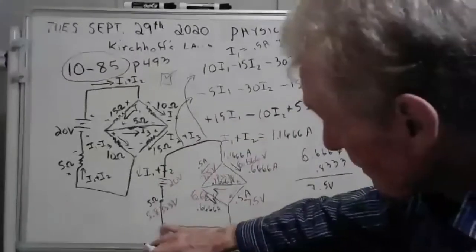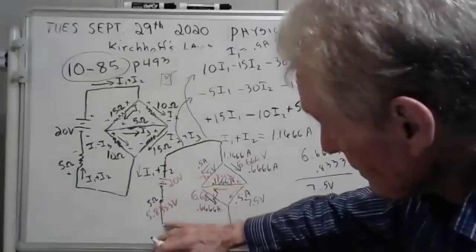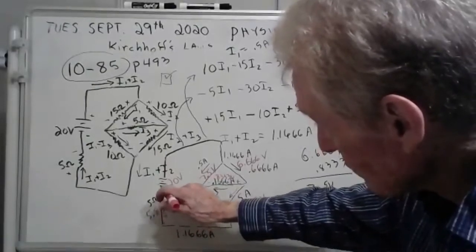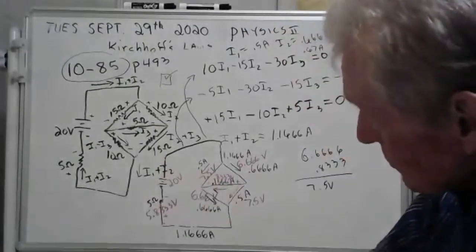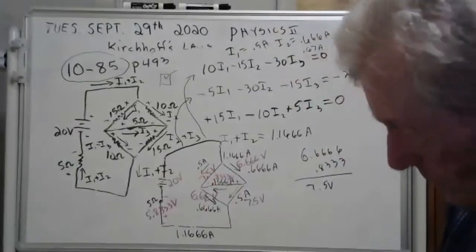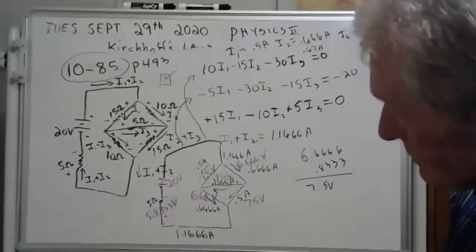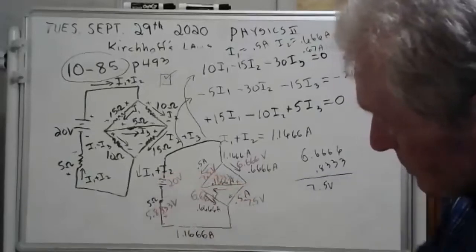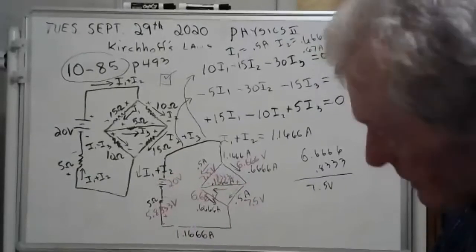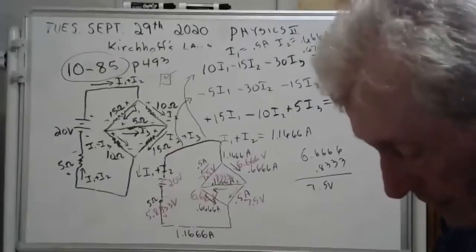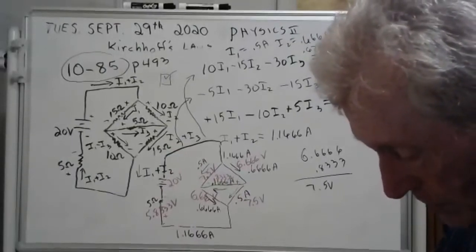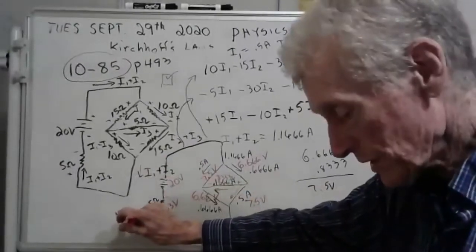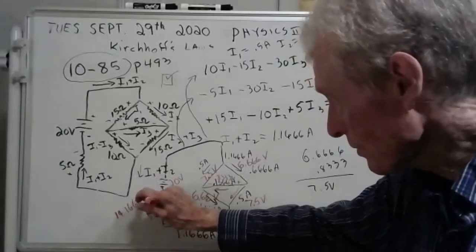Now let's check this out. If you go from here to here, see, this is plus minus, do you understand? But this is minus plus. So what you got there is around, well, I'll figure it out. It's around 13 something. 20. Do you understand? This is plus minus, but this is minus plus. They're acting against each other. Take 20 and subtract 5.8, bunch of threes. Going from here to here, what you've got is 14.1, a whole bunch of sixes, volts.